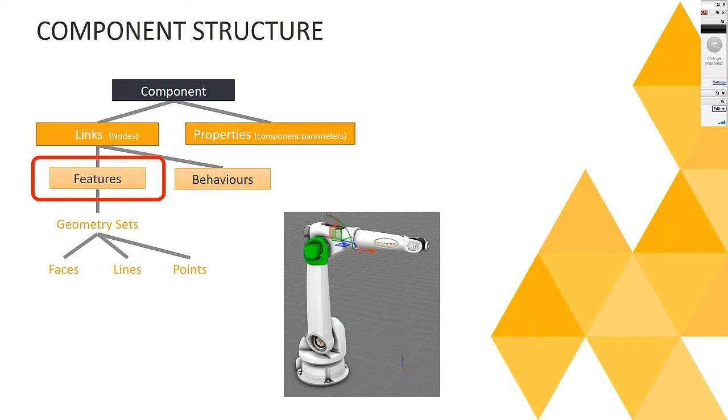In this particular example, we have now highlighted this top part because this robot is a parametric robot where we can define the link length. So the parameterization of this component has made so that the middle section feature is actually made longer and shorter as we change the link length, but this end will stay the same, which is highlighted. So there is multiple features inside of this one link.